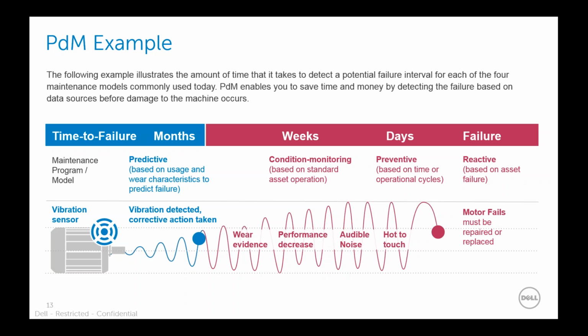So really what this is showing is if I can predict when a motor is going to fail within days or weeks, that is going to save on my overall predictive maintenance cost at the end of the day, because I'm not going to have to send maintenance people out onto the floor when a catastrophic failure happens. I'm going to be able to schedule and take care of that motor prior to that catastrophic failure ever happening, and really react based on the information that I've received by modeling and looking at what's going on over a course of time.